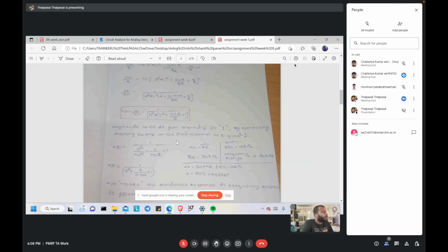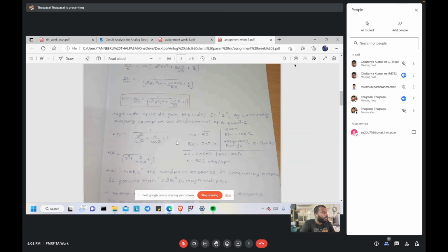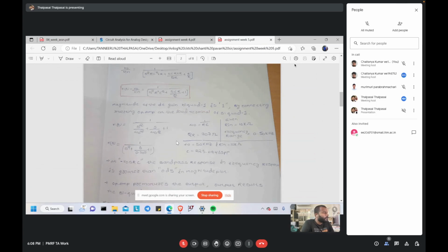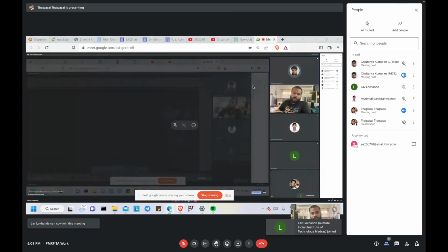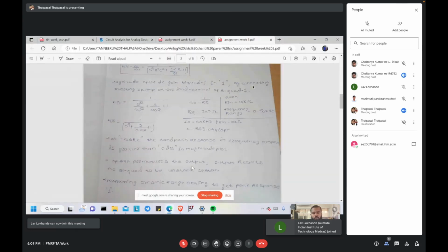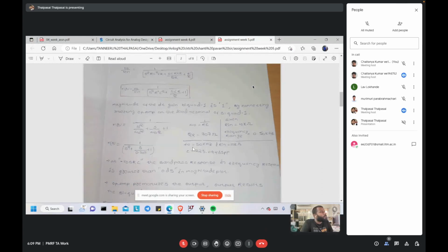Now here you have to decide the Qs. So how have you decided the Qs for the sixth order Butterworth? For biquad one, I decided according to this, sir. First you have to decide the Qs for all of the biquads, right? Yes, sir. For biquad one, it is 0.707, sir.